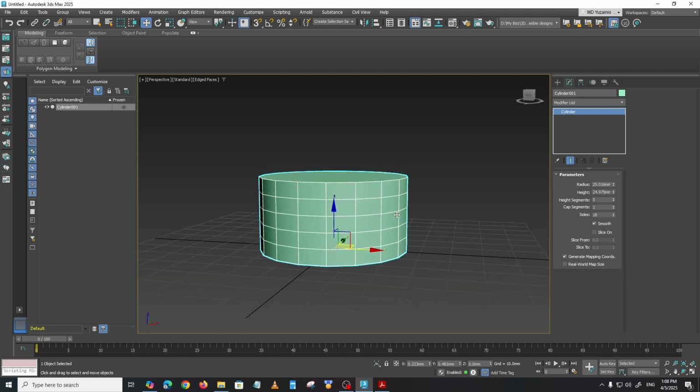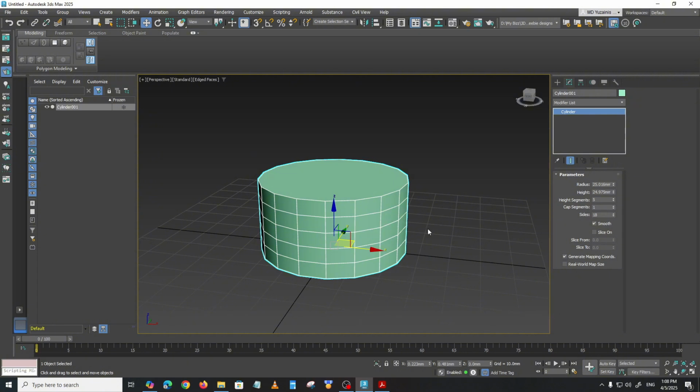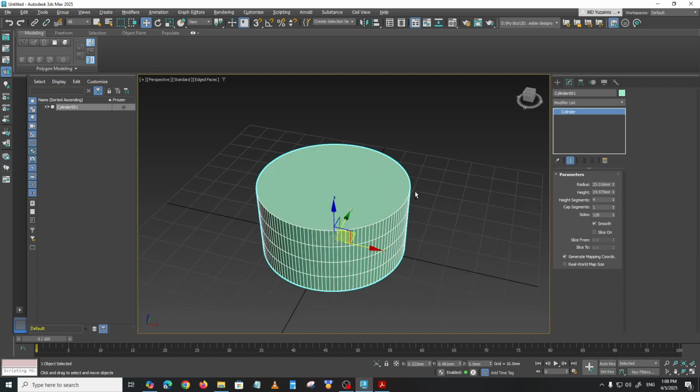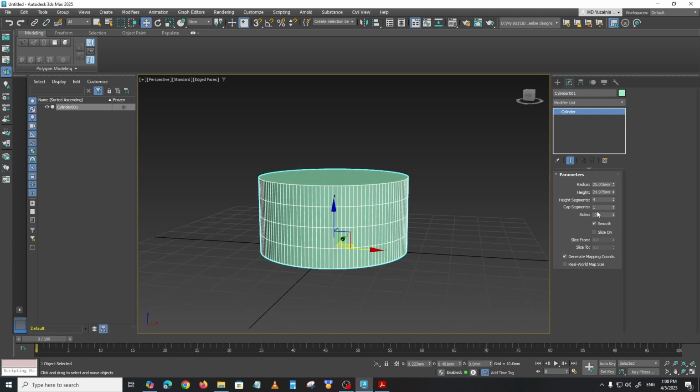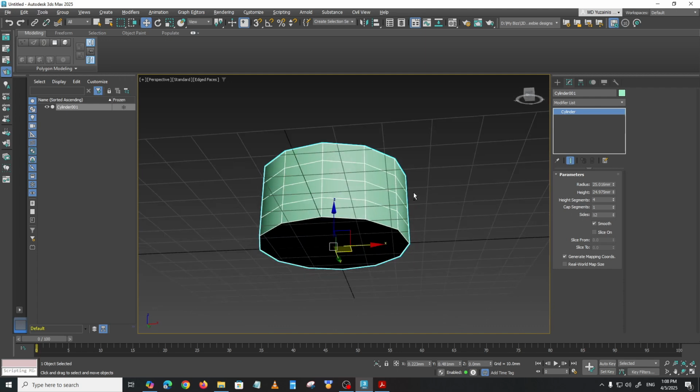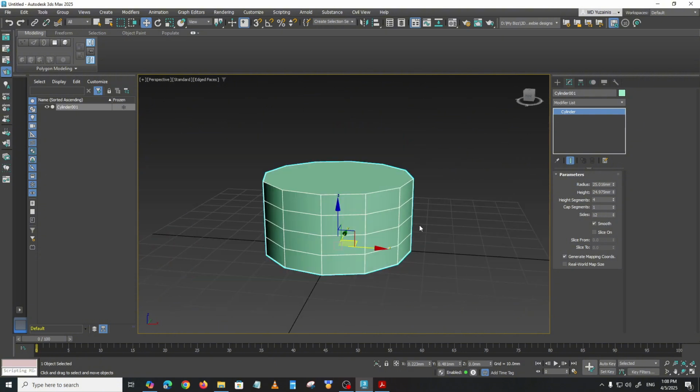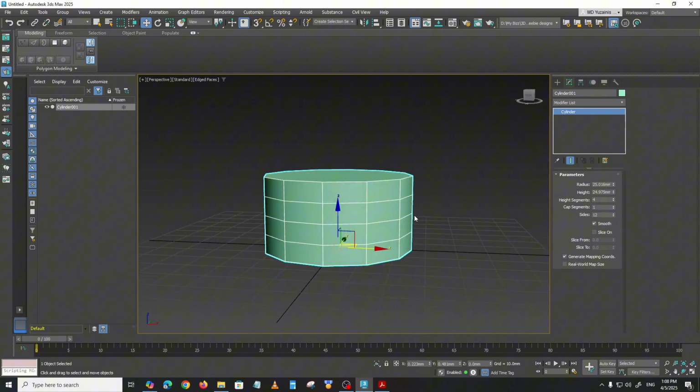and it's advisable that you do not start with too many polygon faces. So segment here I'm gonna put 4, and the side you will be thinking, oh, I want a smooth rounder bowl, so I want 128. So that's softer, that's rounder, right? But don't worry about that. You're gonna start with much less than that, which is just 12 sides. Later you'll see we're gonna add a modifier that will make it into a higher polygon or high resolution model.